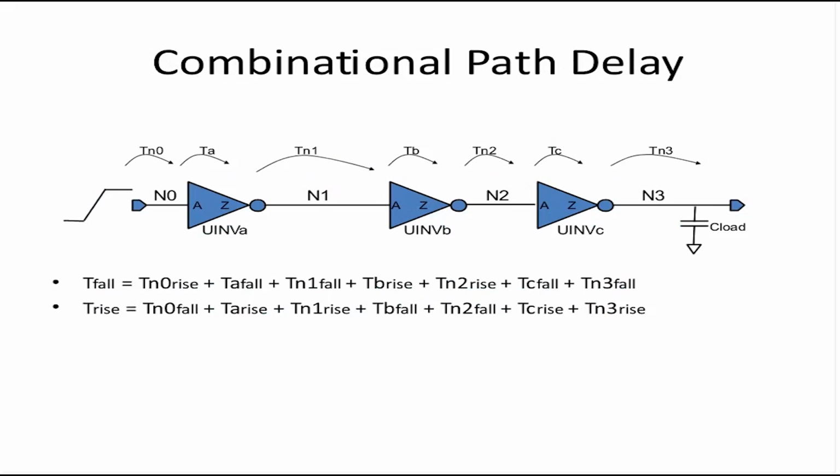So how is the combinational path delay calculated? We did one example when we were calculating the clock latency in the last lecture. For example, PrimeTime wants to calculate the fall delay. Every node will have a fall delay and a rise delay, because the standard cells and nets are not symmetrical in terms of rise and fall.